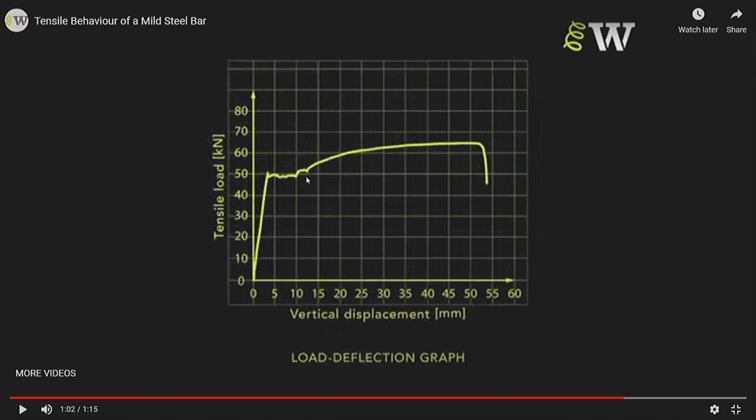And how much it will do depends on whether the material had been stressed to the yield before or not. So if this is the first time it is yielding, then it shows a larger yield plateau. But if you have yielded it, taken out the load, and then put the load back again, you will not get a sharp or distinct yield point like that.